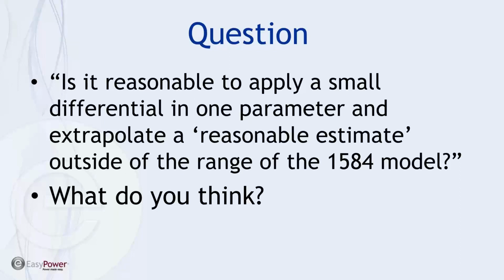The example that they give in the standard, the most obvious example, of horizontal in a closed box, is when you have a low voltage power circuit breaker racked out of the connectors behind it, but it's still sitting in the enclosure itself. The place where it left the bus, the place where it was terminated, that's going to be a horizontal in a closed box. But the model doesn't take into account these other elements that are blocking the discharge, and so that's another reason to consider use of the model in your particular application.